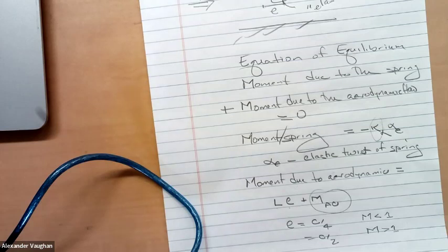It turns out, if I'm at Mach number 0.1, which is our wind tunnel, up to maybe even 10 degrees. If I'm at Mach number 0.9, it might be 1 or 2 degrees. See, that's another difficulty with transonic flow. The range of linearity for which these aerodynamic models apply is much smaller in terms of the allowed motion before you get into the non-aerodynamic.